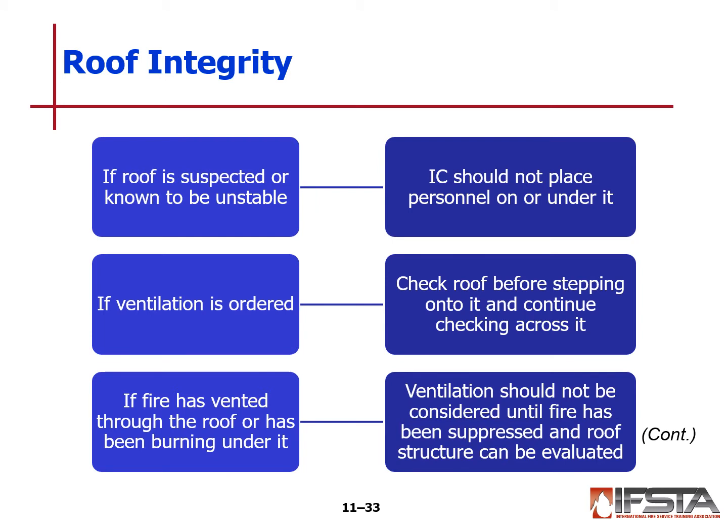The integrity of your roof. If the roof is expected or known to be unstable, then the incident commander should not place personnel underneath it. It makes sense, common sense. If ventilation is ordered, check the roof before stepping out onto it, and continue checking across it as you go. If fire has vented through the roof or has been burning under it, ventilation should not be considered until the fire has been suppressed and the roof structure can be evaluated. So if it's self-vented, it's a concern.